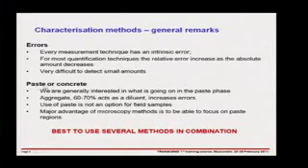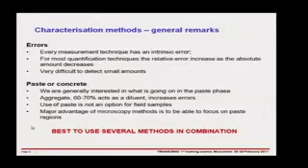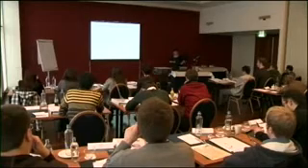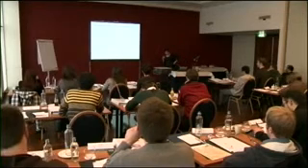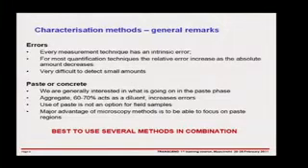The second remark is about paste or concrete. So in general, we're always interested in what's going on in the cement paste phase. That's where everything's happening. But if we're looking at concrete, we have 60 or 70% aggregate, which generally dilutes our signal and therefore increases our errors. So that's one good reason why we often use paste rather than concrete to get better measurements. But we have to, of course, remember that a cement paste is not exactly the same as concrete because of this interfacial transition zone effect, which I showed you earlier.